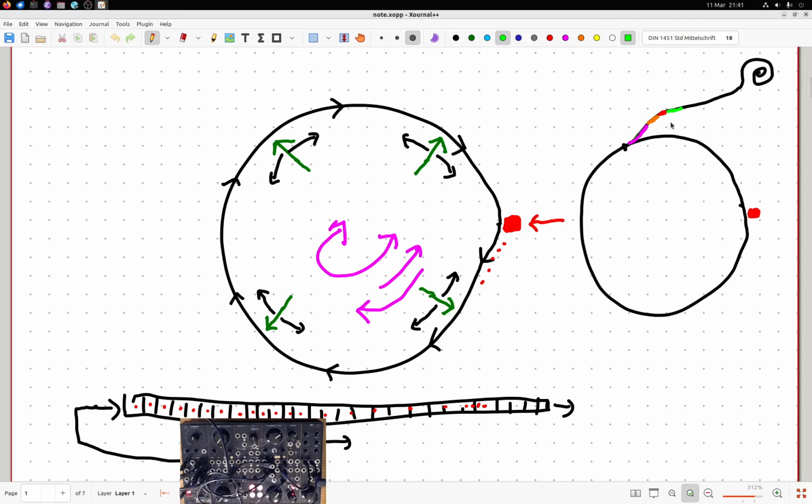The way to think about this is, instead of just having a single loop of the tape loop going around and then all of the spare tape trailing off into the distance, I want to wrap the tape loop around twice and then have the rest of it going off into the distance. What that means is the record head will actually write to 2 points on the tape at once. It'll write to the position in the active loop that we're dealing with, but it will also write to a whole other length of the tape as we go along.